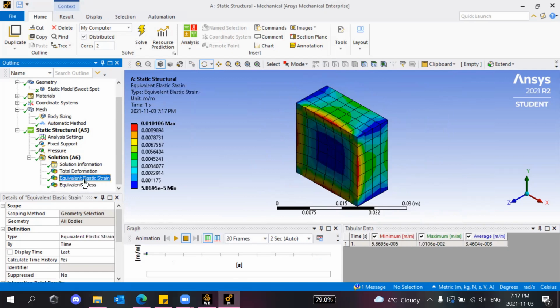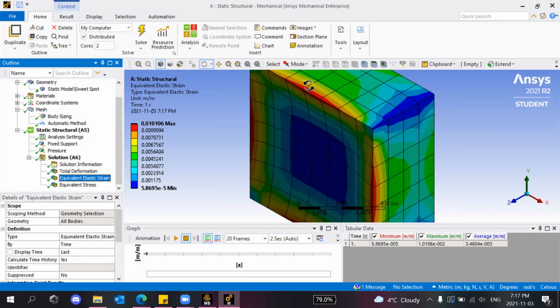It's important at this point to ask yourself if these results make sense. So for example, I had my sides fixed at these 4 faces. So it would make sense that I would be seeing some peak stress right here, because that's probably where my door piece will be breaking off, right? One thing you would also want to make sure is whether the max stress occurring over here is less than or greater than the yield strength or the failure strength of the material, so that with the pressure you're applying, you're actually achieving the stress that you're getting.